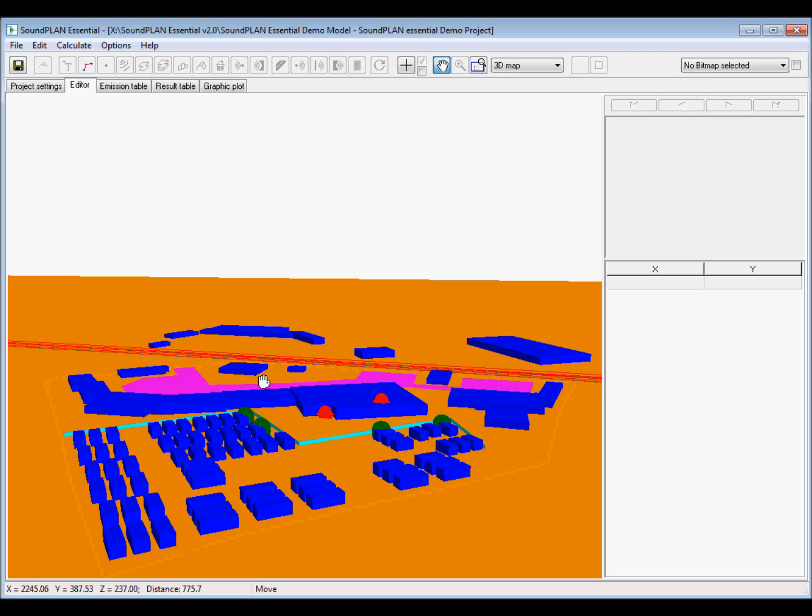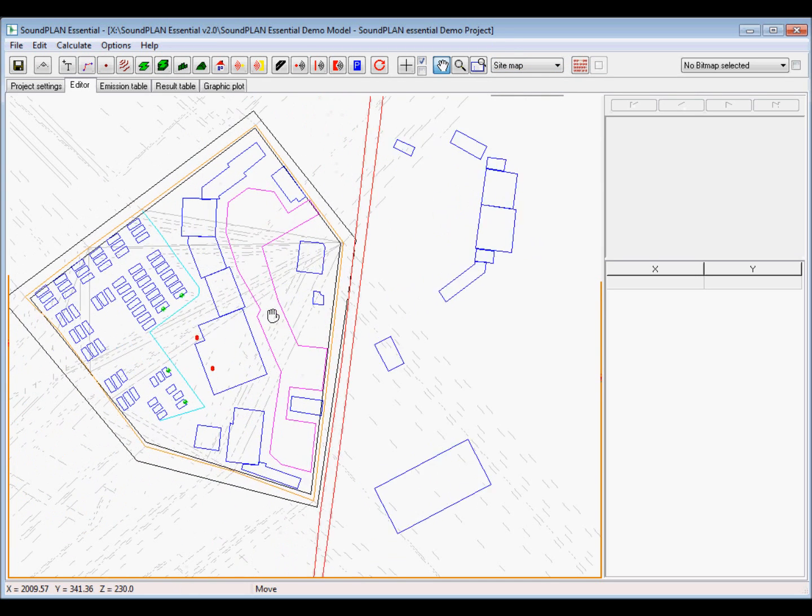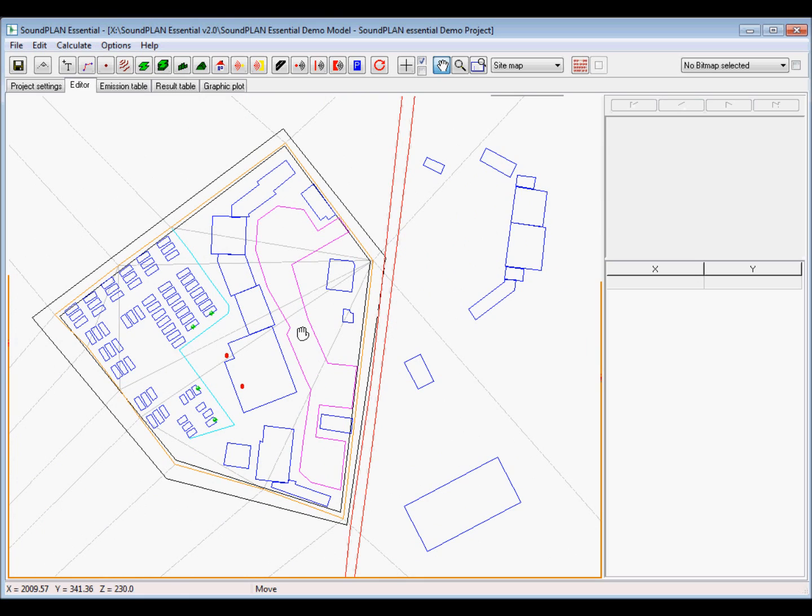And so here we have different objects that are entered. You can see at the very top, we can save the data that's entered. We can turn on the right angle mode when we're digitizing from the aerial map. There's a text object that we can enter, for example, the house numbers. Then we have a general line. These are basically just general object types. And then following are object types that define the geometry, either in terms of a point elevation, so there is a spot height, or line, contour lines.